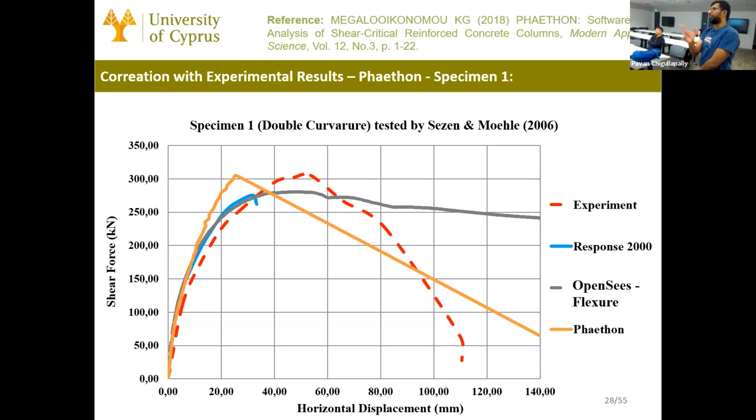Okay. And one more thing: in the OpenSees model, what materials and reinforcement models did you use? Yes, it's the Menegotto-Pinto law for the steel and the Mander law for the concrete. No, I mean in Concrete02, which concrete model? Yes, and it's the Menegotto-Pinto. Like which ones are they?